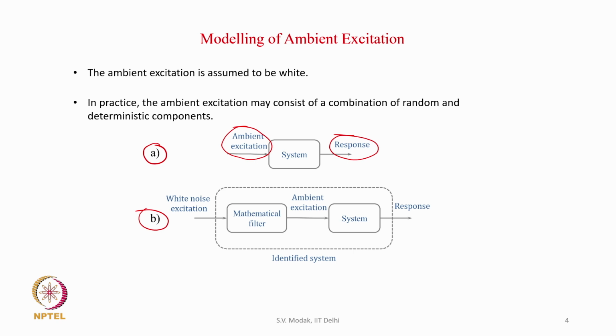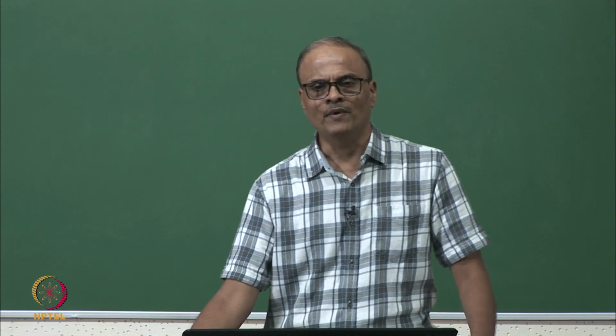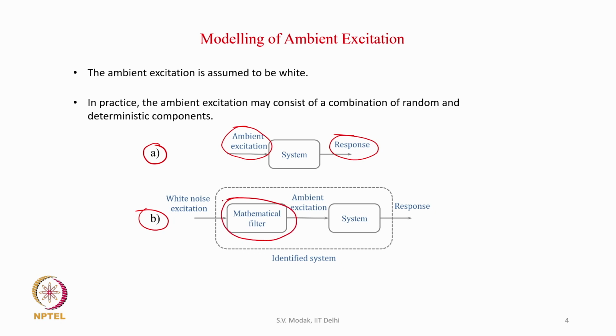Operational analysis assumes the ambient excitation acting on the structure to be white. So, this assumption amounts to the existence of a mathematical filter before the system. You can see this is the mathematical filter which converts the white noise excitation into the actual ambient excitation, which acts on the system and generates the response. So, when the operational analysis analyzes this response, it effectively identifies the modal parameters of the combined system. You can see this is the combined system, represented here as the identified system.